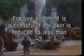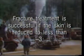In such cases, it is imperative that a pre-frac evaluation be run in order to estimate a value for the permeability. The success or failure of the fracture treatment can be determined using the calculated skin factor. As a rule of thumb, the frac treatment is successful if the skin is reduced to less than -3.